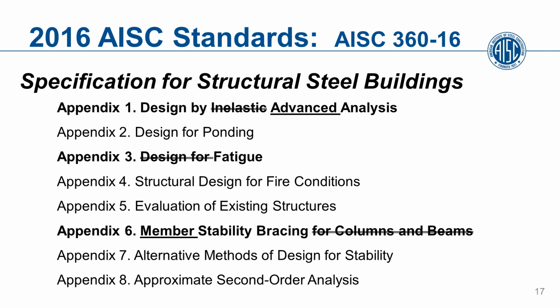It also addresses issues for fabrication, so you have to keep that in mind at the same time. Appendix 6 has been retitled from Stability Bracing for Columns and Beams to Member Stability Bracing, again because Appendix 6 now addresses not just columns and beams, but other members as well.